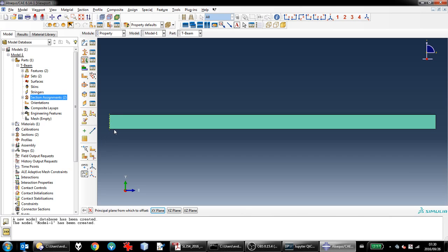So obviously to create one 200 mm to the right, we do the same thing again. We select the principal plane again, the XY plane, but we're going 0.2 to the right. And then we also want one for our central support, so from this point we're going to go 7.2 meters to the right end of that support. So XY plane again, 7.2 meters. Right, that's it.